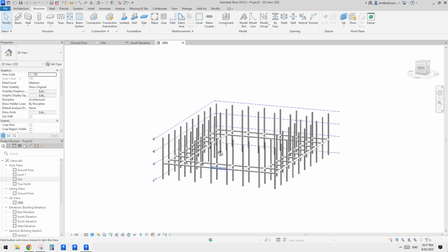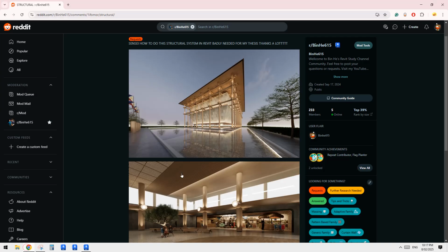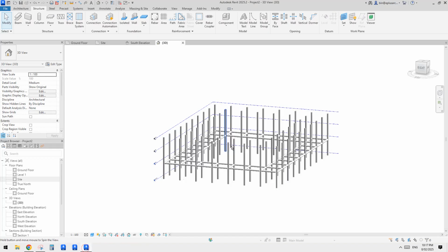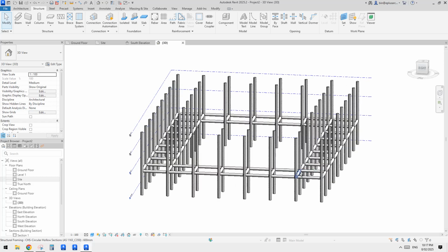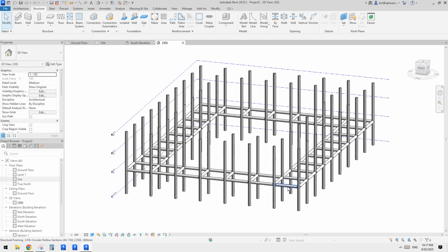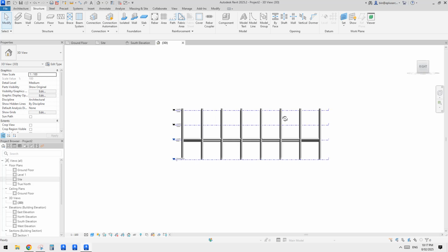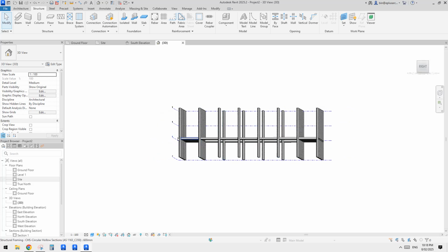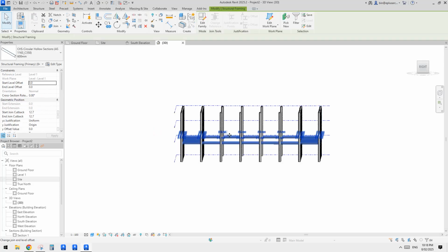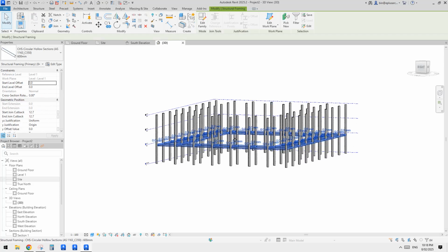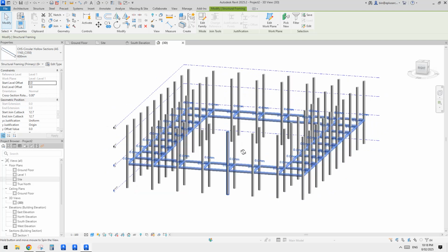Oh, actually, you can adjust all the beams' overhang a little bit, and then after that you can copy, or you can also copy first and then do the adjustment, right? It will be the same. So in this case, I'm going to just copy them. So you can select all the beams in this model.